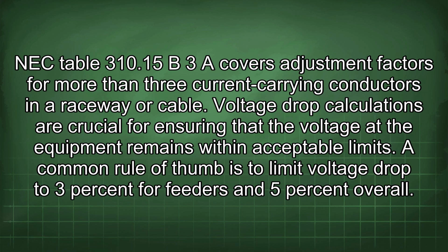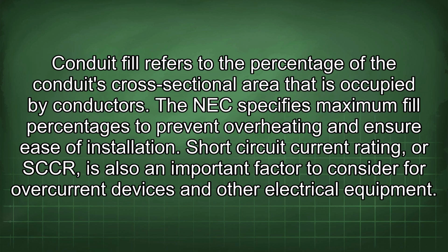Voltage drop calculations are crucial for ensuring that the voltage at the equipment remains within acceptable limits. A common rule of thumb is to limit voltage drop to 3% for feeders and 5% overall. Conduit fill refers to the percentage of the conduit's cross-sectional area that is occupied by conductors. The NEC specifies maximum fill percentages to prevent overheating and ensure ease of installation.